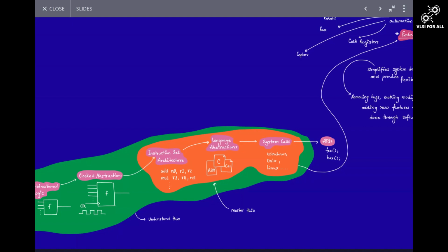The second thing is you want to communicate some data between the tasks, and you want to synchronize these tasks. Let's say two tasks are using some common variable, some global variable. When one task is using that global variable, the other tasks should not use it. So how do you synchronize this? Synchronize between tasks. The concepts are semaphores and mutexes. Task synchronization, you need to understand.